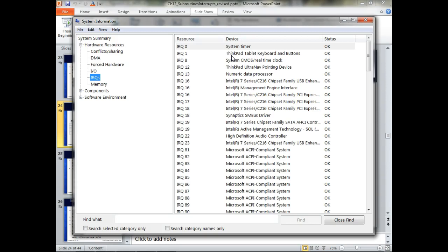Even though I can type pretty fast, I'm still in a millisecond world, and my processor's in a nanosecond world, right? So we could probably do 2,000 things between my keystrokes. Even in that little amount of time, it's not scanning the keyboard. It only scans it when I hit a key. So if that's true, then our PLCs have to have the ability to allow us to set up interrupts. And that's what this is about.